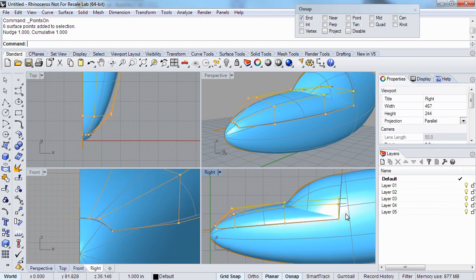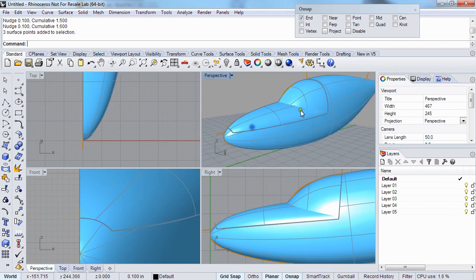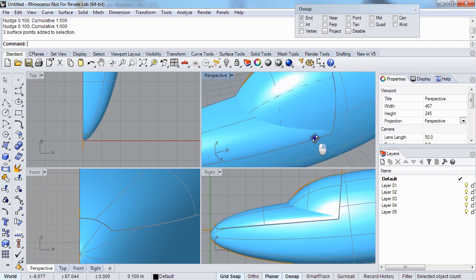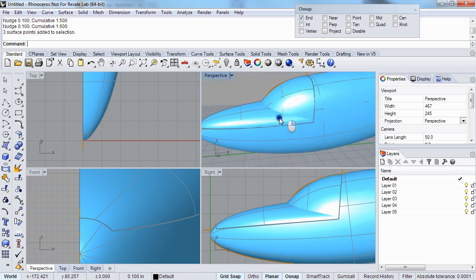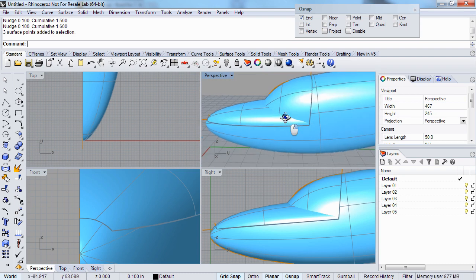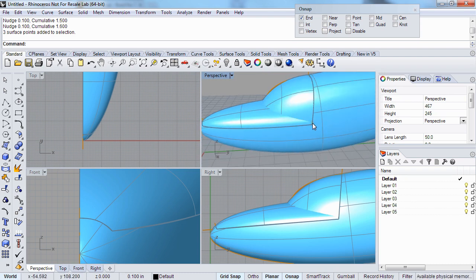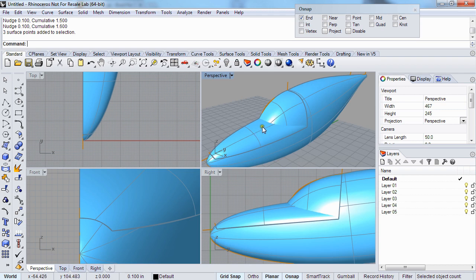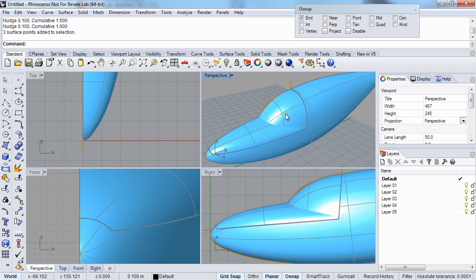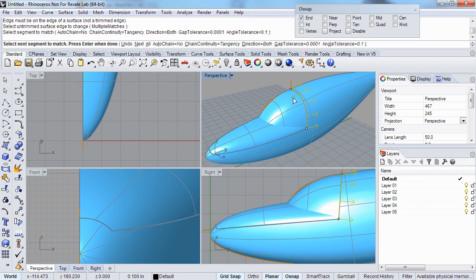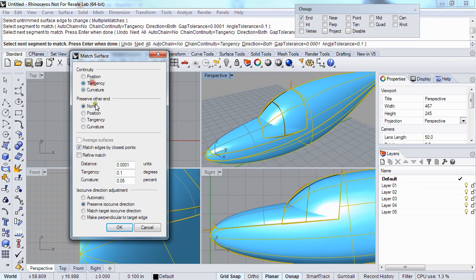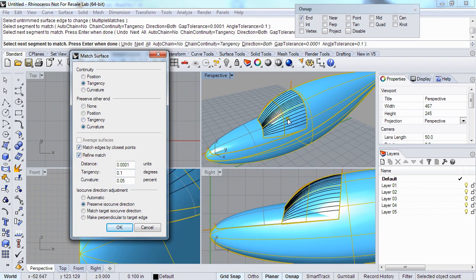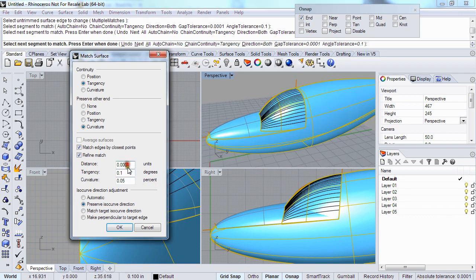So, all right, let's do a little bit more point editing, then we'll call it a day on it. We'll nail it down to this point. Now, it can still get very tricky. This little corner here, where these two surfaces intersect and come together, can get kind of nasty. You have to be very careful about what's going on there whenever you're finishing this off. But anyway, let's match up this here, curvature.